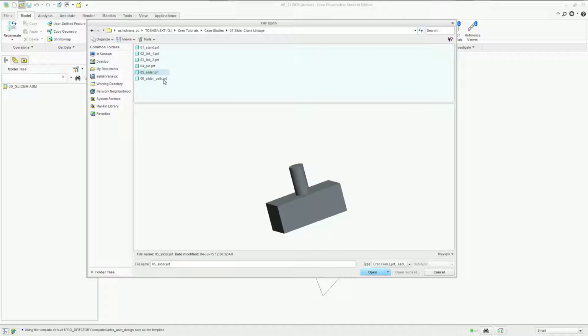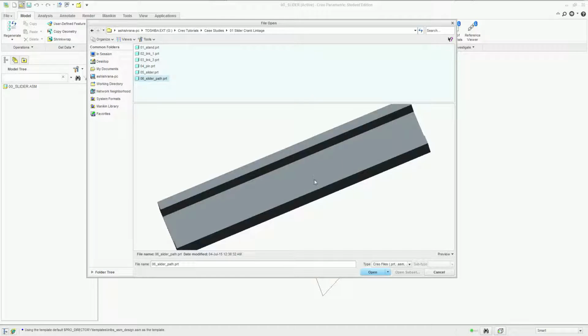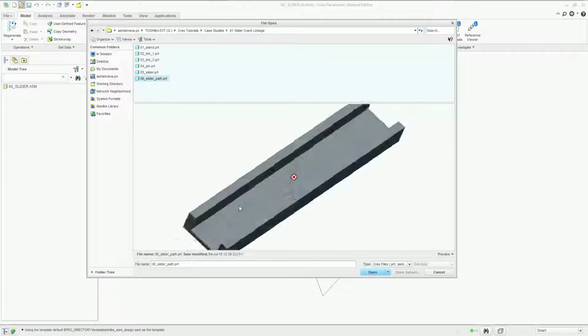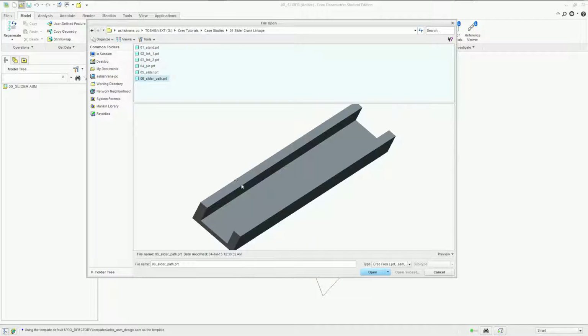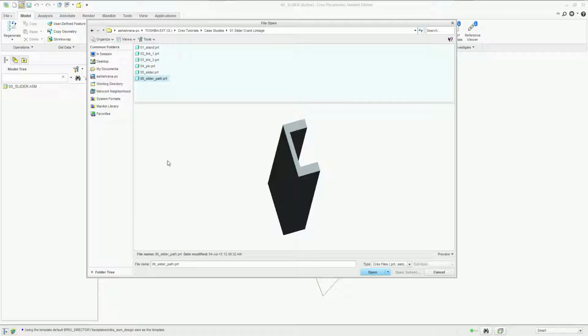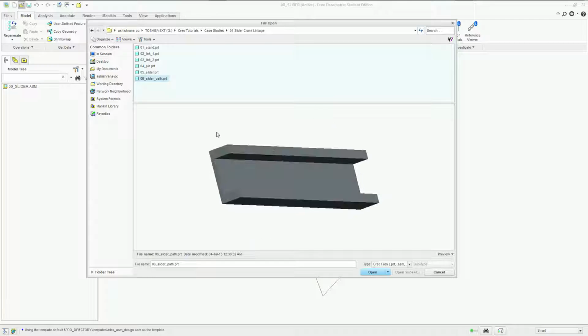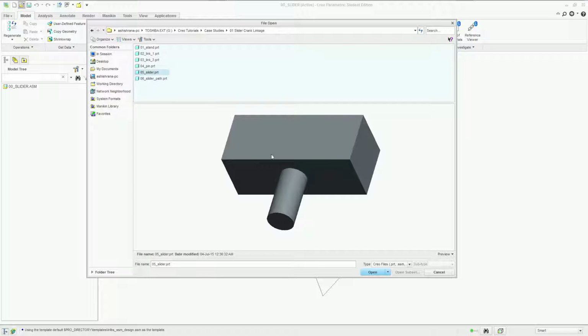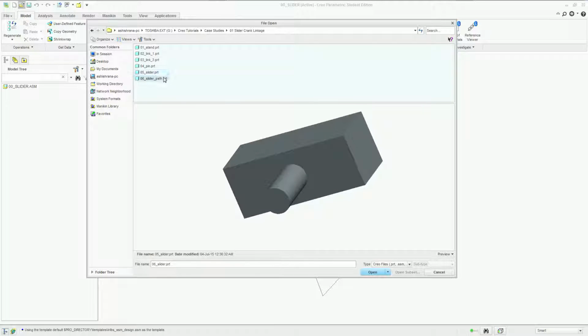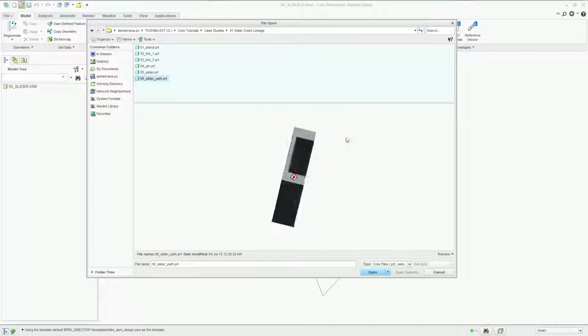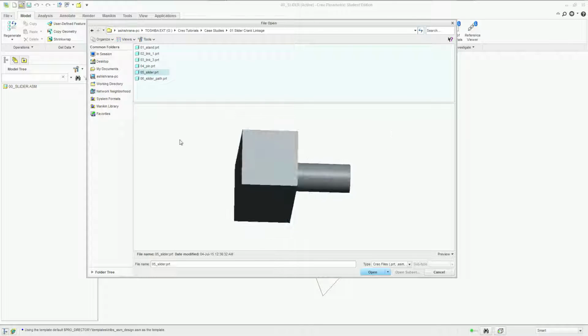And then we have a path for the brick to slide in, and that's what this is gonna serve as. It's a very simple part. Again, just make this shape and extrude it outwards. Not very complicated at all. Just make sure you dimension things properly. Make sure the path, so this distance right here, when you make this shape, this gap, should be the same as the width of this brick right here.